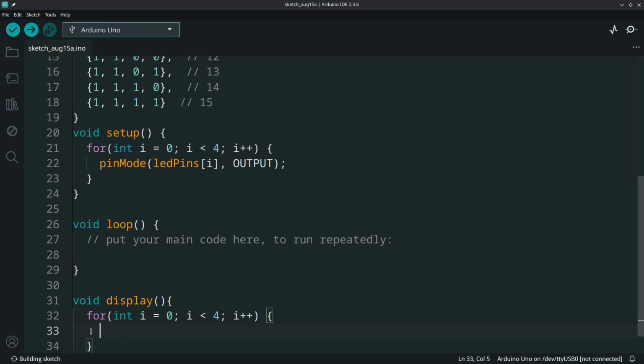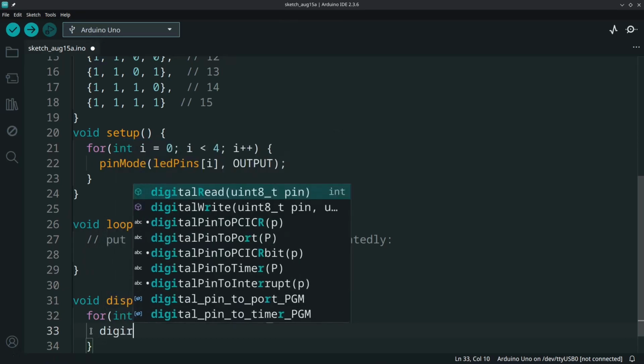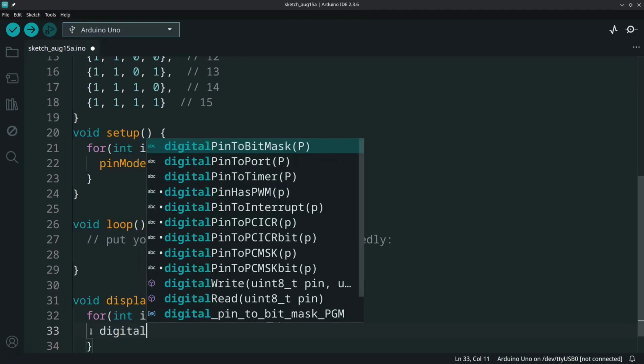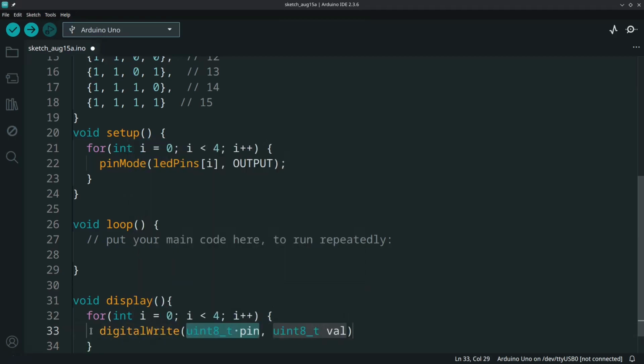But now this is where things change. Now, how do we write to turn on our LED from our previous code? We turn it on by using digitalWrite, because LED digital can take only 1 or 0. So we use digitalWrite here, not digitalRead.